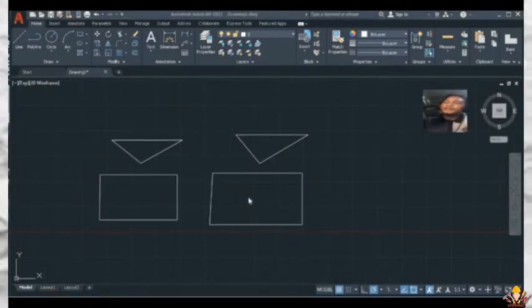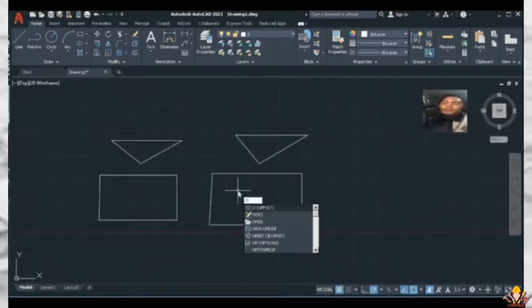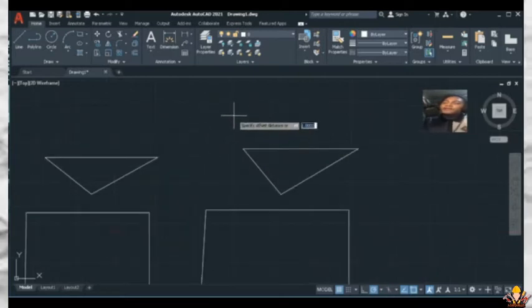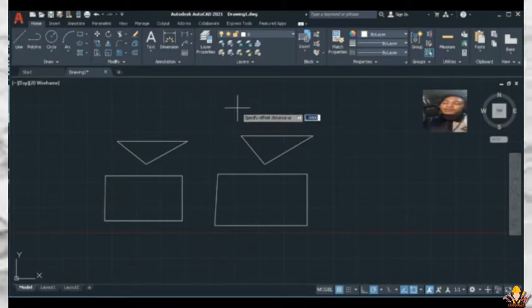So moving on to the next one, I want to show you guys how to use the offset command on AutoCAD. In order to use the offset, you just have to first press letter O on the keyboard and then press enter, and here I have to put a specific distance for my offset, and I will just select 1 meter for the offset distance.